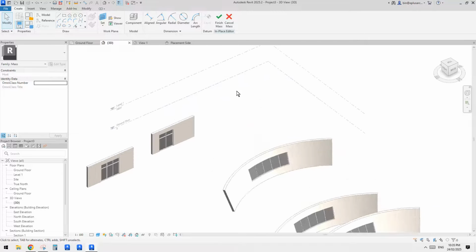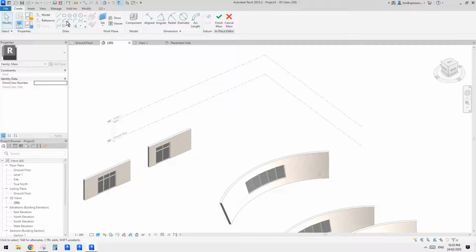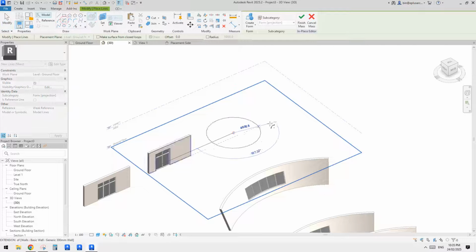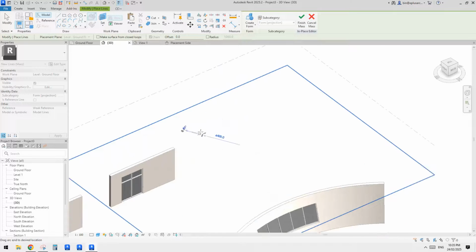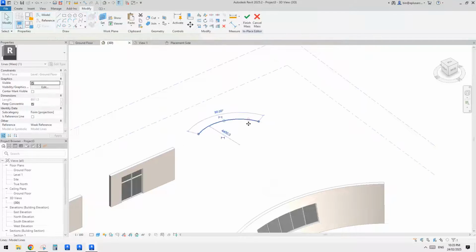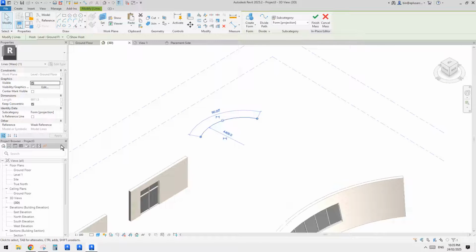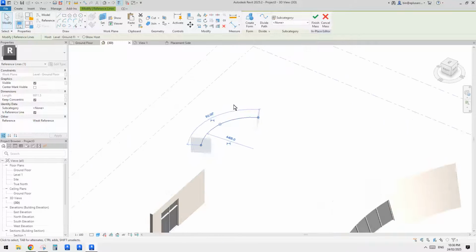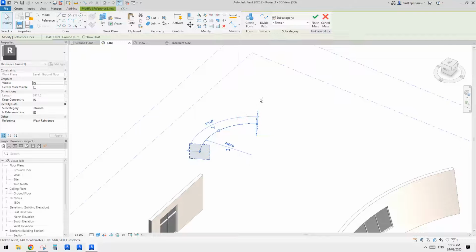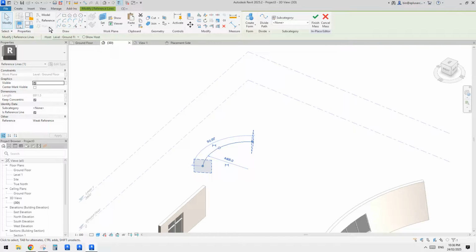Okay, so what I'm going to do is let me just do a star and arc and set world plane first. Sorry, onto the level. And maybe I'll just do a star and arc, something like this. Okay, for example, this. Or maybe make it a reference line. And then I'm going to copy with Control C, and then paste in the same place. Or actually, I'm going to directly paste it onto the level, up level.